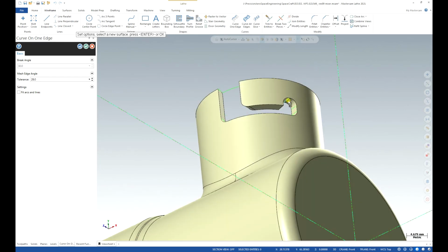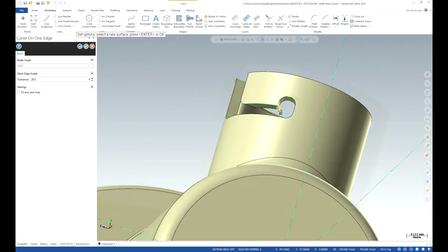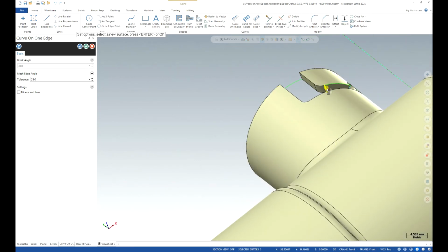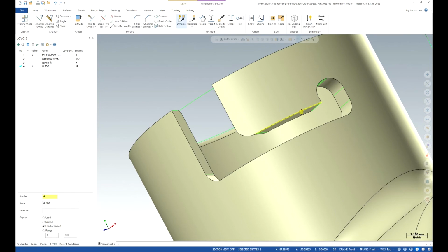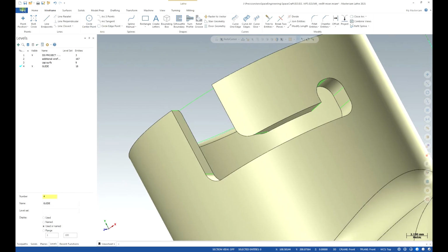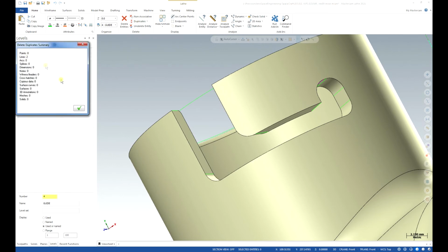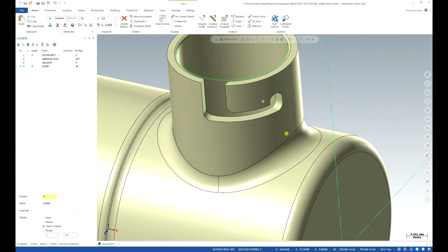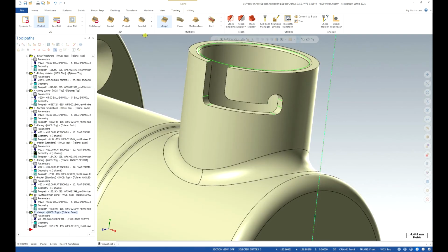Let's select this guy. Oh, I pressed that multiple times, so I'll have to delete that. This guy, and this edge, and this edge of the surface. That looks good. I'm going to remove a few lines. Go to home, delete duplicates. You see 2 lines have been deleted. Okay, after creating our tool axis control lines, we can go and start our multi-axis toolpath.